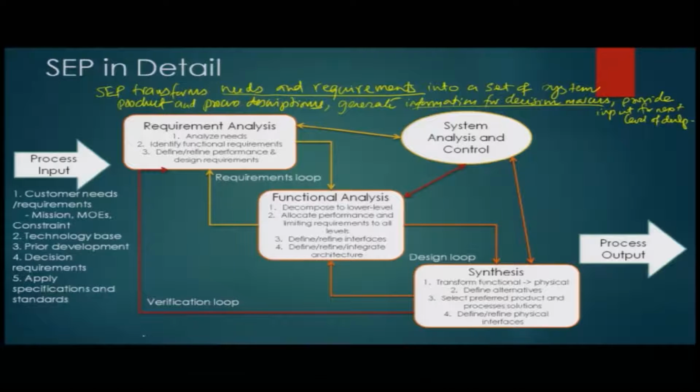this is what the landing gear should do, this much big tires we require, and all those other aspects were taken care of from that. So that functional requirement of taking off from paved and unpaved surfaces gets translated to the type of wheels that need to be used in the UAV, the type of landing gear that needs to be chosen, the ground clearance, and the damping on the suspensions. All those things have to be decided as part of that.